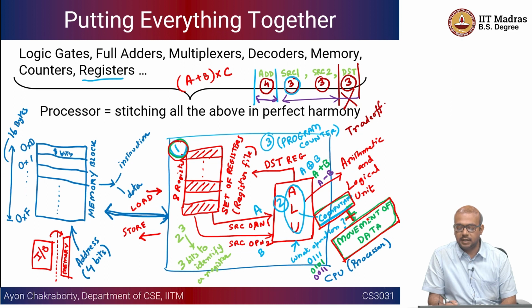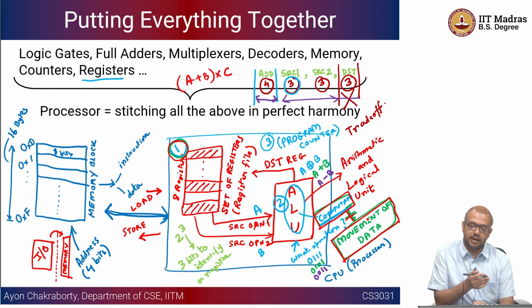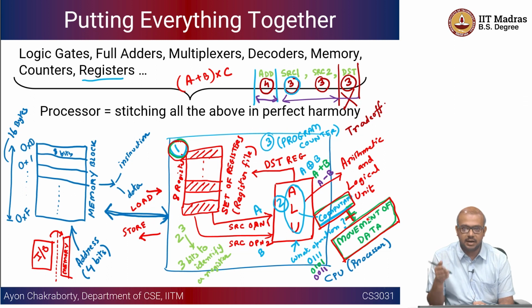As you can understand, this computation, movement of data, and other things like getting the instruction from the memory, moving it to the registers, pushing it to the ALU, and so on, all need some kind of central orchestration. The program counter is getting updated, the program counter goes to the next value. This entire thing is not manually done, right? If you look at the execution of a program step by step, we will revisit this to understand what the exact steps are, but at least for now you can have some intuition that the program is executed in a finite number of steps.